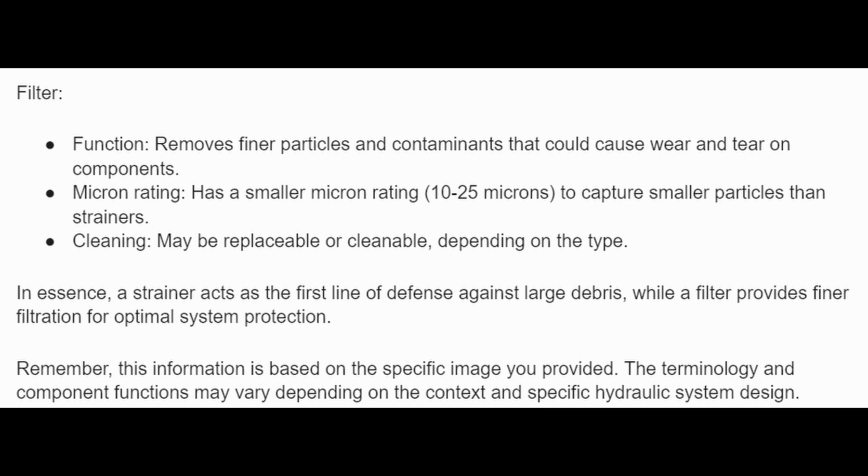Its micron rating is smaller, 10 to 25 microns, to capture smaller particles than strainers. Cleaning: may be replaceable or cleanable, depending on the type. In essence, a strainer acts as the first line of defense against large debris, while a filter provides finer filtration for optimal system protection.